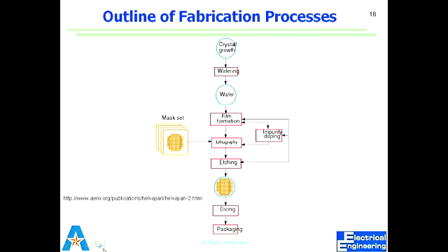So the design of the process, how we integrate the whole process, has to be optimized. As a simple example, if I put a metal on the wafer already, maybe to make an interconnect, can I now do 1,000 degrees centigrade oxidation? Think about it. No, because the metal will vaporize, right? So the whole process has to be streamlined to know what can come after what. But if I have metal, I can do PECVD, plasma enhanced CVD, to deposit oxide. I cannot grow oxide then, but I can deposit oxide.